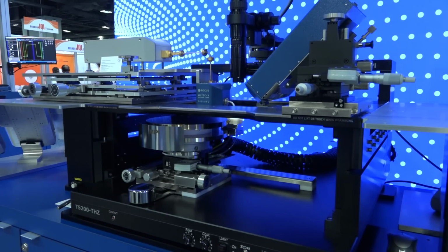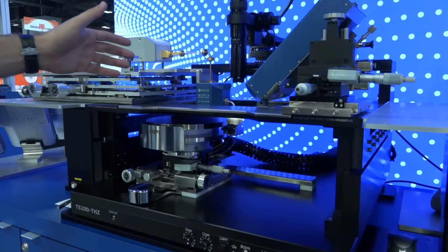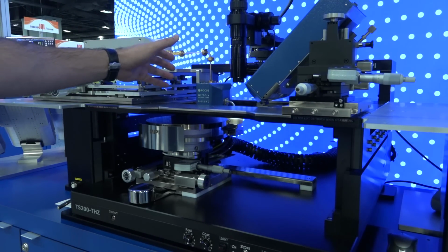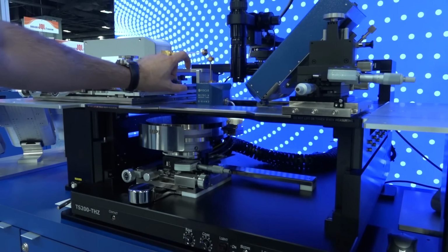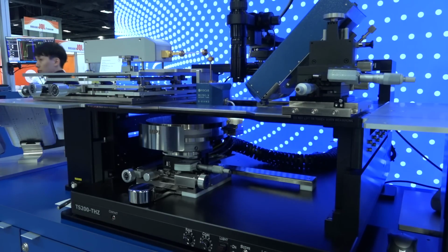So now we're beginning to see more and more vendors push the boundary of what you can do with load pull at higher frequency ranges. D-band is somewhat of a common frequency range nowadays, and you can have a D-band tuner that fits very close to the probe. A few advantages. This unit itself has about 0.9 coverage on the Smith chart, but of course the losses of the probe would limit that. But bringing this so close to the probe interface means that you can get as much of the tuning capability on the Smith chart from each of these modules as possible.